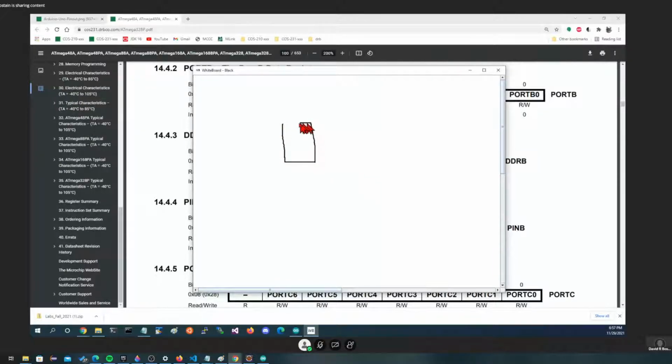In the world of tri-state logic, where we have multiple guys trying to write to a bus, we take away the totem pole part of their output, leaving them only with the ability to ground the wire. Meaning he could ground it, or both of them could ground it, and the wire would show ground. Any other time, it's just floating around showing whatever it wants to show.